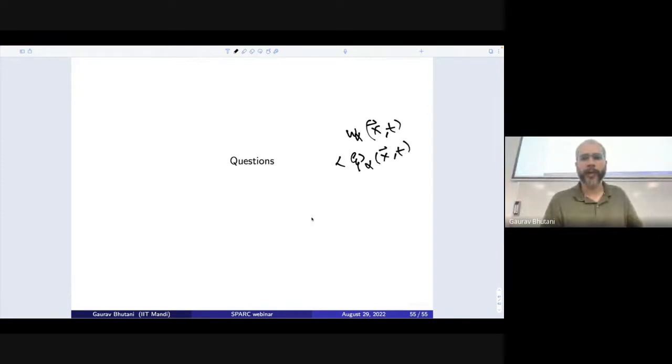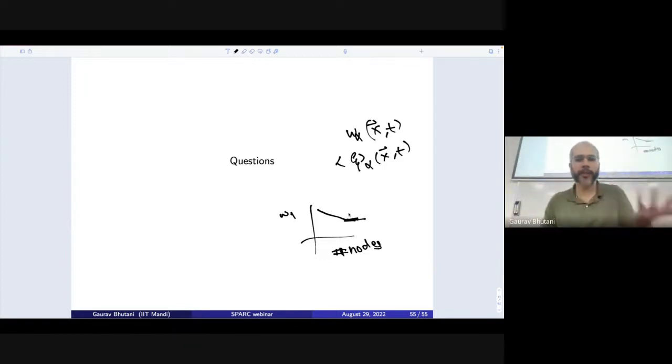So we can take the number of mesh nodes, and take one of them, let's say W1, and see that as you increase the number of nodes, ultimately it should settle down and become flat. It's a mathematical idea. There's no link with the physics here. So mesh convergence is a very mathematical thing. We are solving for scalar equations, so we check for the convergence of scalars.